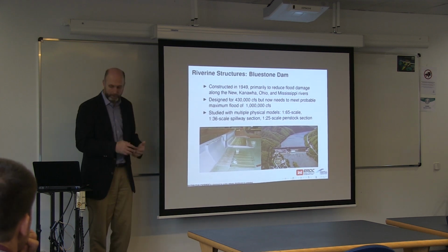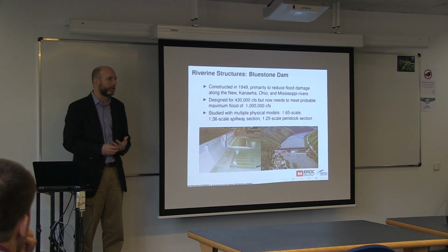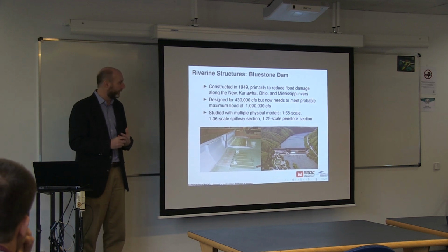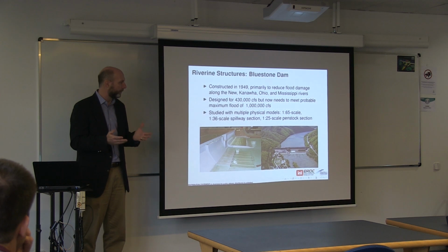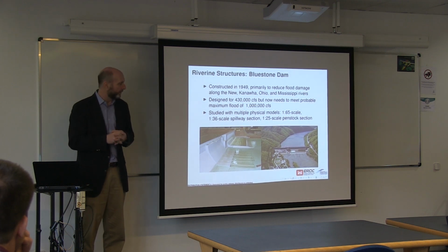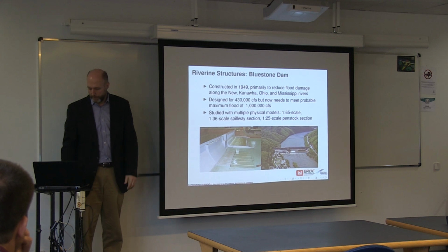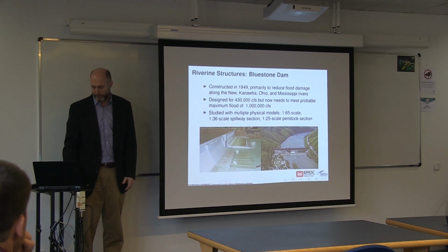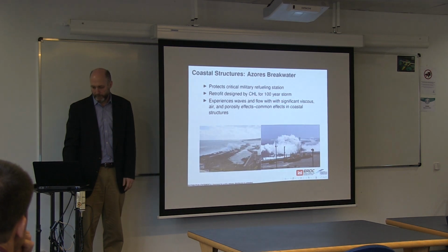So scour is a major problem, but predicting it is very difficult. As we'll talk about a little bit, there are good riverine models for looking at sediment transport in 2 dimensions over large scales, but once you're dealing with a very 3-dimensional problem, the evolution of that scour is more difficult to model, obviously, in 2D, so you really need to resolve the 3-dimensionality of it. So that's one of the motivations.